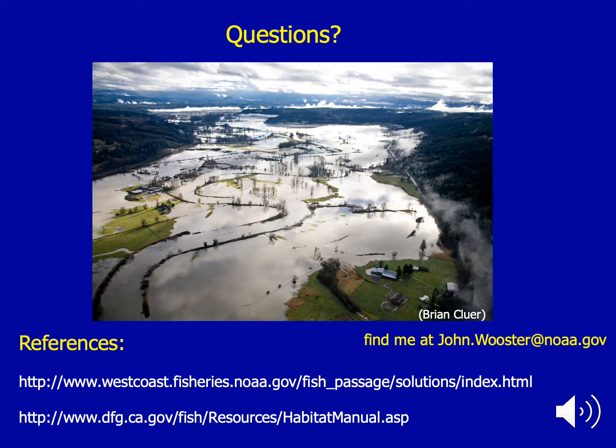And probably one of my favorite tools now is to use historical aerial photos. This is now generally a pretty easy exercise with Google Earth. Here's where you find your meandering and island braided type of systems, where you tend to see 1% slopes or less. The main difference between a meandering channel and island braided is that usually meandering is a single thread system. Island or anabranching or anastomosing type systems have multiple threads.